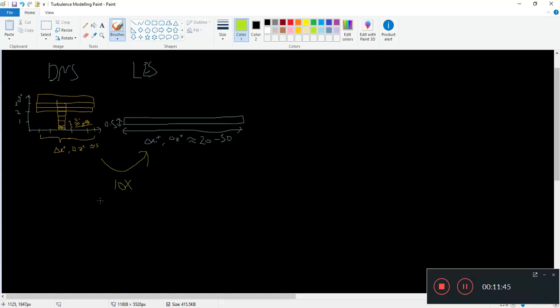So you can kind of infer, based on how you scale the boundary layers, you can scale the LES grid by 10 times the Kolmogorov length scale. That means one LES grid will be able to fit 10 of the smallest eddies in there. Alright, so that's what LES is talking about.